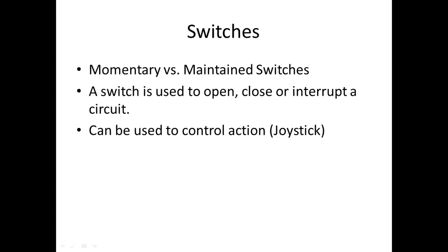Next up, we have switches. Switches come in two types, momentary and maintained. A momentary switch is something that you would press to reset something, where a maintained switch is more like a light switch, where you would turn it on or turn it off.